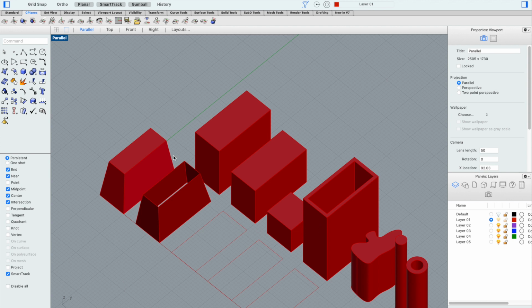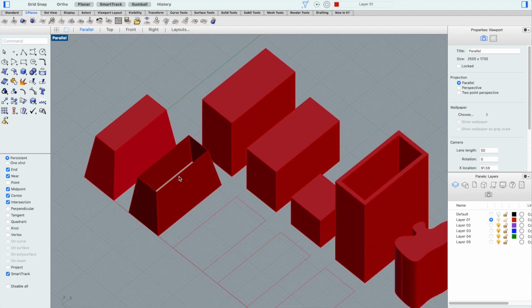I think it is probably maybe the best command in Rhino because it fixes pretty much every single question that I get that's like, how do I make this thing have a top on it, or how do I close this shape? It can almost always be solved by sweep2, I find, if you just use it creatively. So sweep2 is an extremely valuable tool.